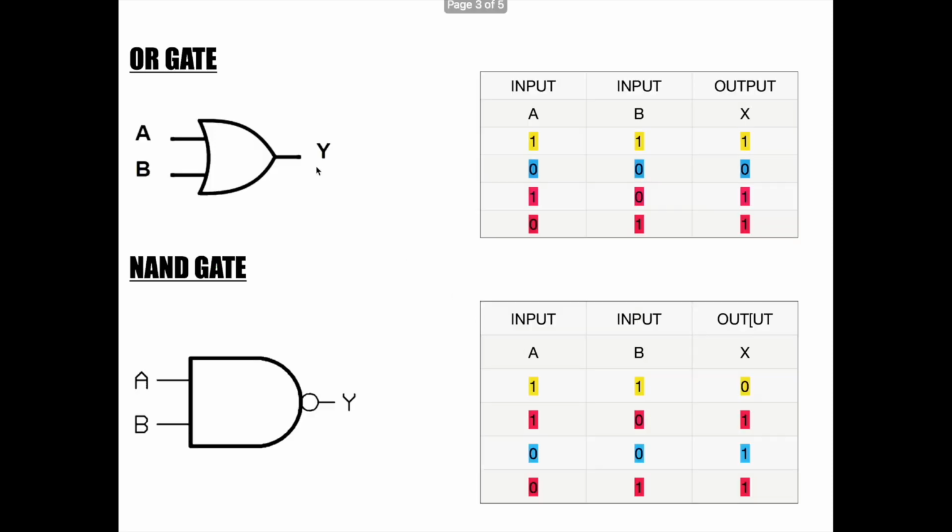The next logic gate is the OR gate. The diagram below this title presents the OR gate. Similar to all the other logic gates, here also we have 2 inputs and 1 output. The OR gate performs addition. This is pointed out in this table. If the inputs are 2 zeros, then the output is also 0. If the inputs are 2 ones, then the output is 1. But if the inputs are 1 and 0, then the output is 1, since addition, not multiplication, is performed.